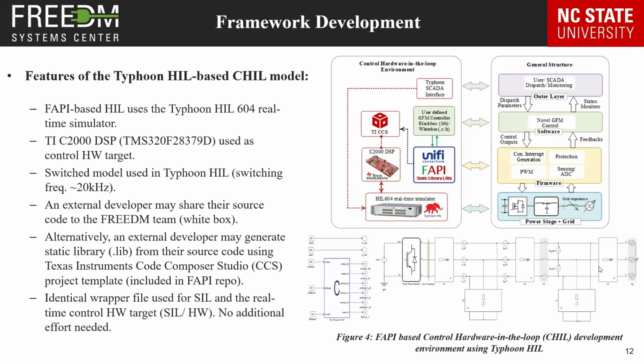An external developer who wants to test a novel GFM controller can use the Code Composer Studio project to integrate and load control code in the TI DSP LaunchPad mounted on the HIL TI microgrid LaunchPad interface. FAPI is included as a static library in the TI Code Composer Studio project alongside the user-defined GFM control as either a black box static library or white box C code.